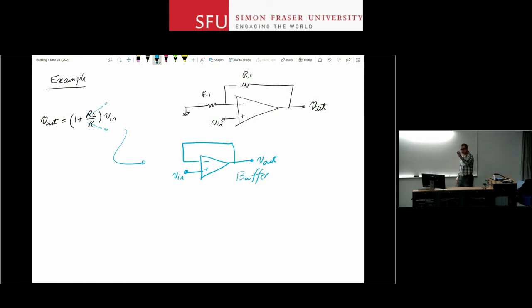And what it does is that it creates a voltage at the output that is hopefully exactly equal to V in, but for whatever you're putting here, what they see is an infinite input resistance. There's zero current being taken from that. However, over here, you can take as much current as you want because the ideal op-amp has a zero output impedance, and therefore you have a voltage source over there. You can measure that voltage and connect it to a speaker and make sound out of that signal, right? Without your source even knowing about it.